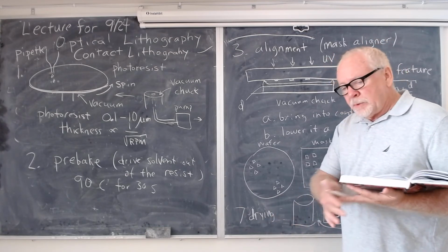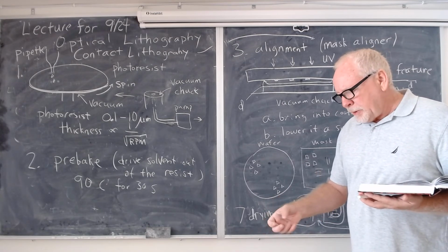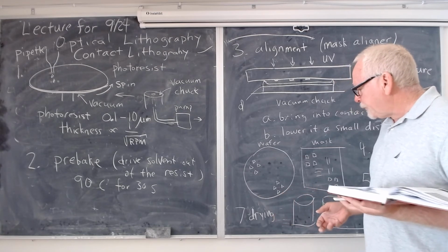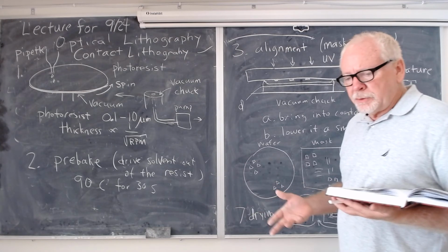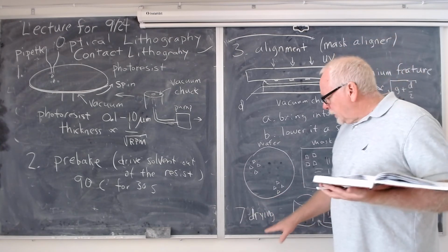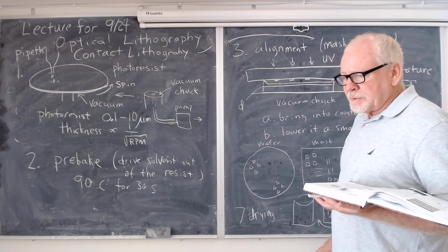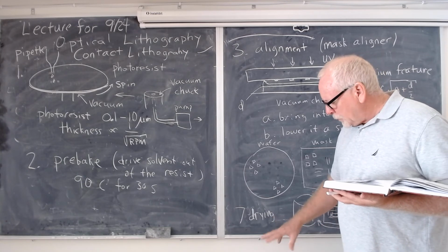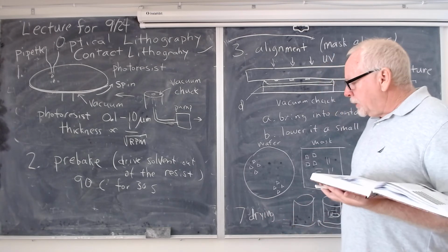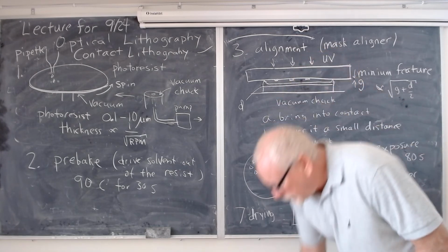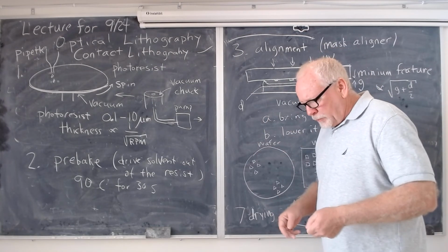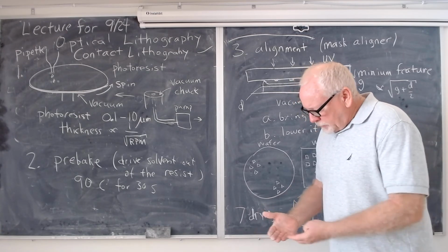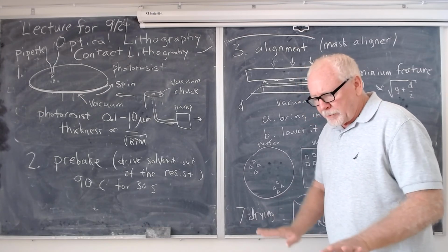And typically that's done with, as Niam shows, a blower of nitrogen air. Usually you want nitrogen because you don't want oxygen blowing on your surface. And I noticed Niam used the technique that I always use, because if you think about it, your wafer comes out wet on both sides, and it's kind of too difficult to hold the wafer and blow on both sides. And so what I would always do is you'd have clean room cloth, paper or something,